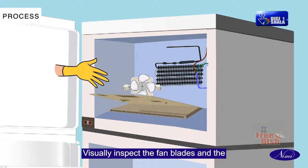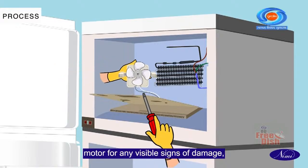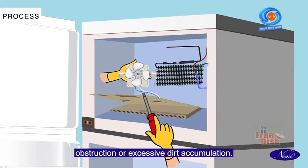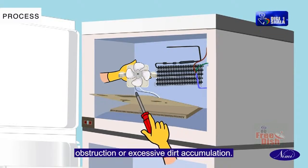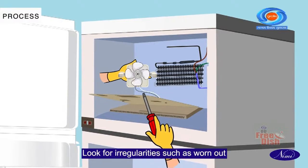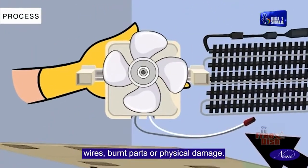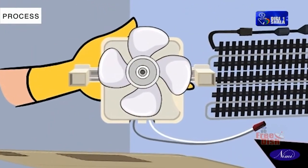Visually inspect the fan blades and the motor for any visible signs of damage, obstruction, or excessive dirt accumulation. Look for irregularities such as worn out wires, burnt parts, or physical damage.